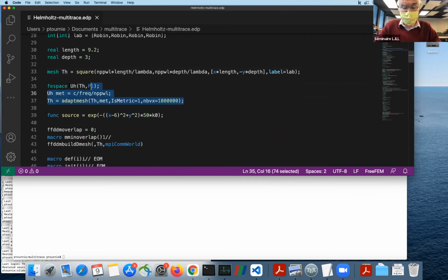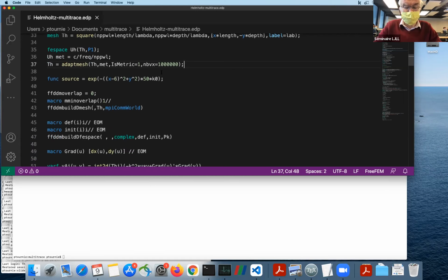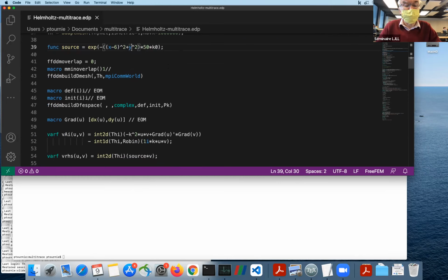This is just doing some mesh adaptation, and I will show the result of the mesh adaptation in the heterogeneous case, with a velocity model coming from the well-known Marmousi acoustic model in 2D. Basically the idea is to adapt the mesh to the local wavelengths. Since I have heterogeneous wavelengths, I have to have a near optimal mesh in terms of mesh size. Okay, and this is my point source, which is approximated in resolution, located at the top of the domain.